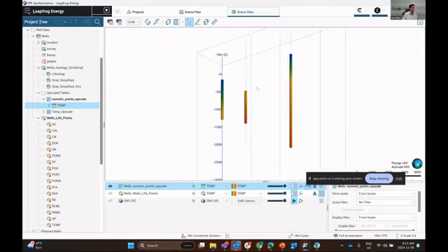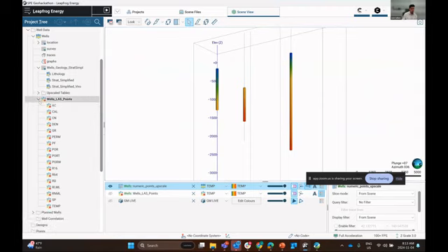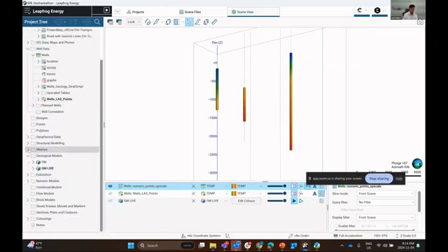So to construct a 3D temperature model, you can construct it from the last points that you see right here, but the algorithm is going to take quite a long time to process because there's thousands and thousands of points. Or you can simply upscale, which is going to average the values associated with each interval. But because there's less data to interpolate, it will be quite a bit quicker of a process. So you can upscale any of the information that you see right here in the last points file.